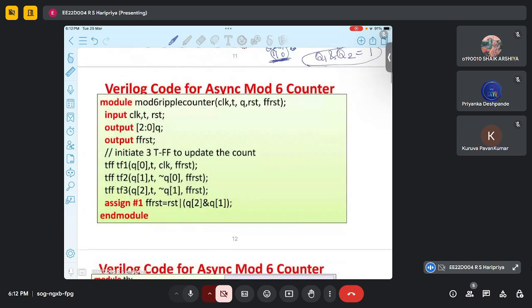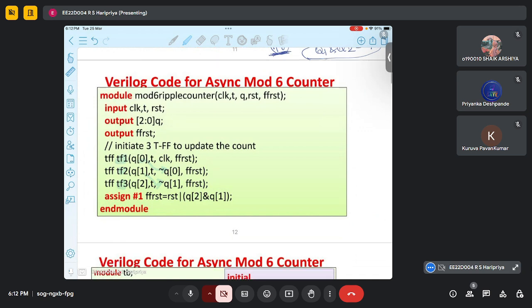Next, the Verilog code. So we need 3 flip-flops, and we are using the T flip-flop, toggle flip-flop, and this complement is the clock here. And this type of counter we also call a ripple counter, because the clock is the output of the previous flip-flop.